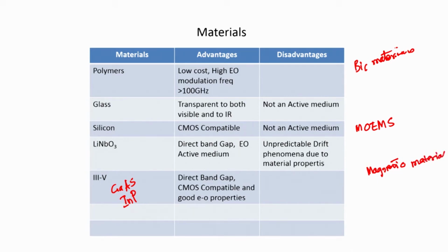Then there are specific materials which are useful for SAW device applications. If you want to use surface acoustic waves, of course, lithium niobate is one of the candidates for SAW applications, but you can think of materials which have got very good acousto-optic effects. And also we need to think of materials which can be deposited over the standard materials to create more devices.